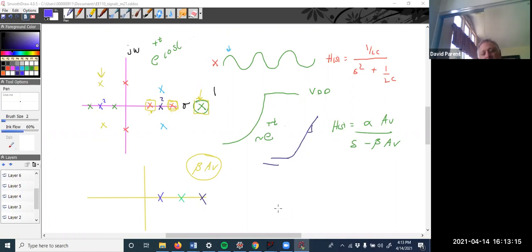But if it's a high pass filter and you need some gain, say you want to multiply it by 10, you're going to need kind of a summer, but it's only summing one thing and then multiplying it by 10. Now for the low pass filter, if you have an odd number of stages, you're going to need something to invert it. Otherwise, you don't need one.